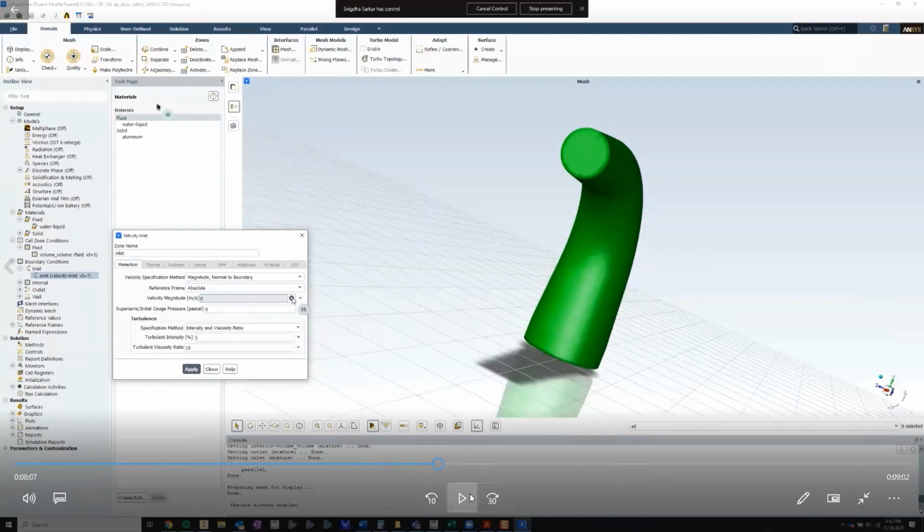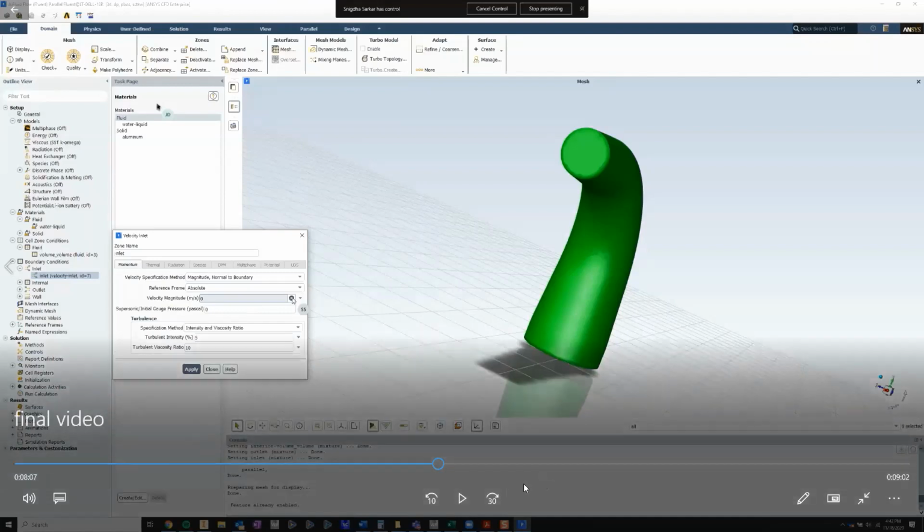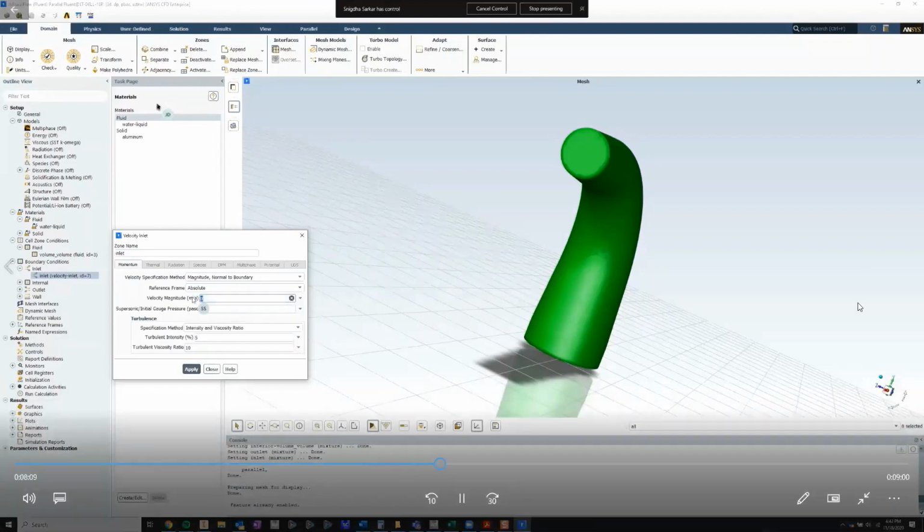But you can always use Fluent meshing for parameters that you set up internally within the Ansys Workbench. Mosaic meshing right now is not available within Ansys meshing. It's only available within Fluent meshing, so that would not work for this demonstration case. I hope that answers the question, and I'll resume the video over here.